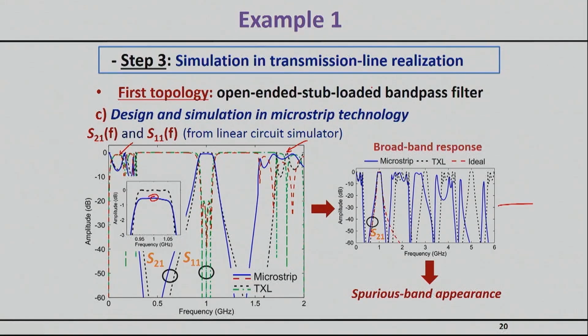And in fact, this figure here is the one that will show you what happens in a very broadband sense. So our resonance is right here, 1 gig. But you will see a repetition of resonances every time these transmission lines resonate. So you will see it at 2, at 3, at 4, and so on and so forth.